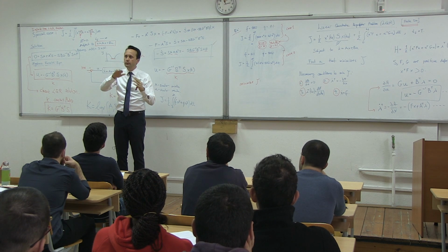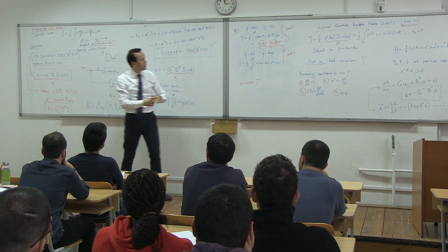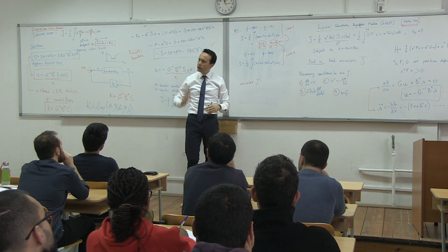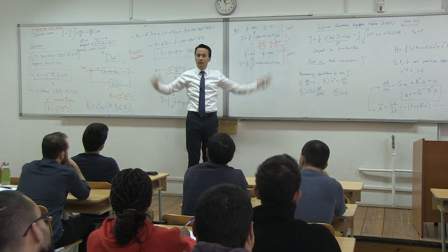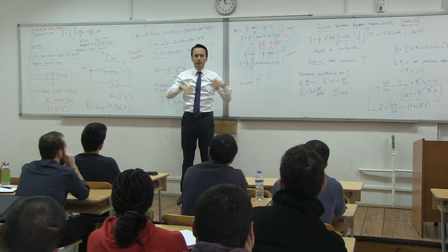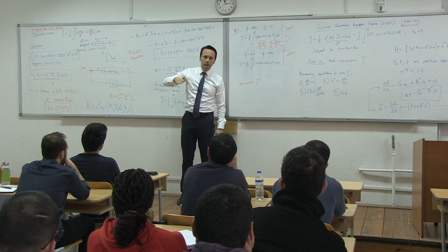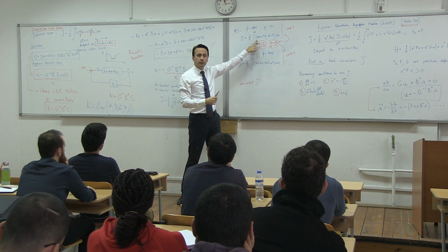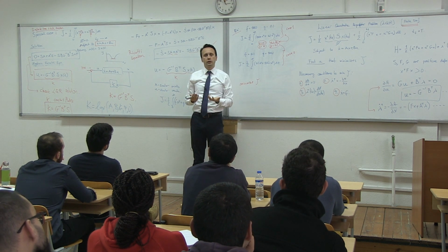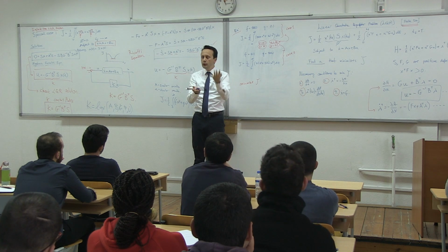Is u important? Should the elevator not move too much? If that's your goal, then you make this one large. Then u will not move too much. But if the elevator doesn't move too much, the aircraft might be moving too much, which means now x will move, the states. You might say, well, I don't want the x moving too much, the states. The u, I don't care. The elevator can do this. Okay? In that case, you might want to have this problem, where you put a large number over here and u can move a lot, I'm sorry, and x's don't move a lot.